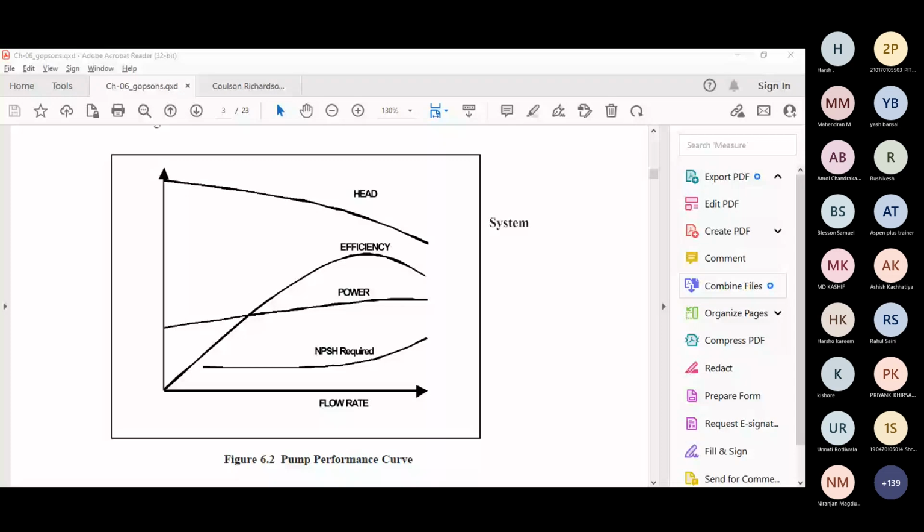So if you change the unit of the head, then the head will change. Suppose I say 10 meters of water column, it is always 10 only. But if I convert that unit to mercury, then it becomes 760. Clear? But your pressure will never change.